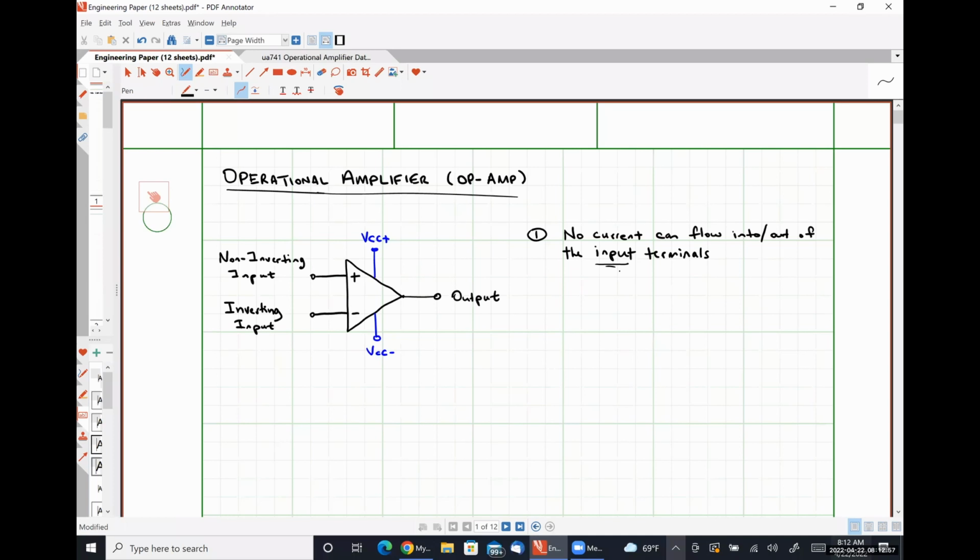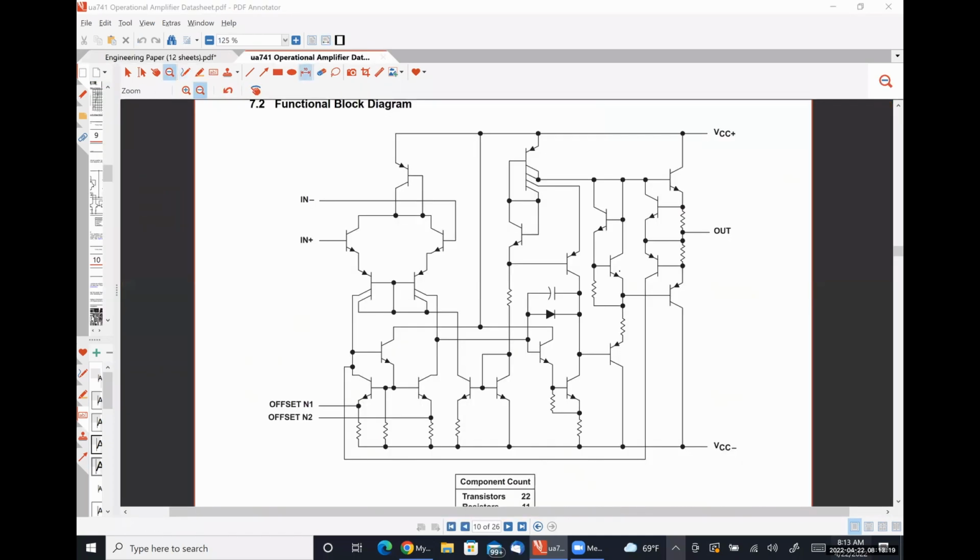Now, the reason for this, which isn't really pertinent to what you're going to learn in this class, but it's kind of an odd thing that we have a section of wire and we're just saying there's no current that could ever flow into them. So the reason for this is what's called the input impedance of the op-amp, okay? So if we look at this guy here, these transistors all have an input impedance.